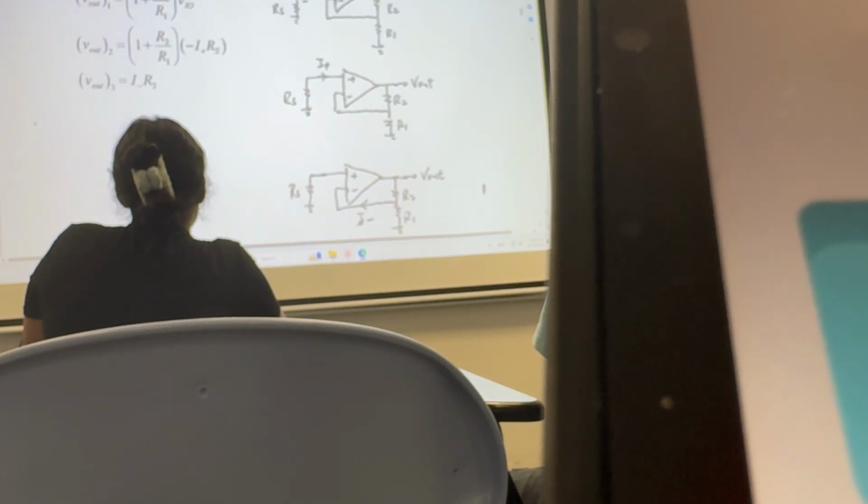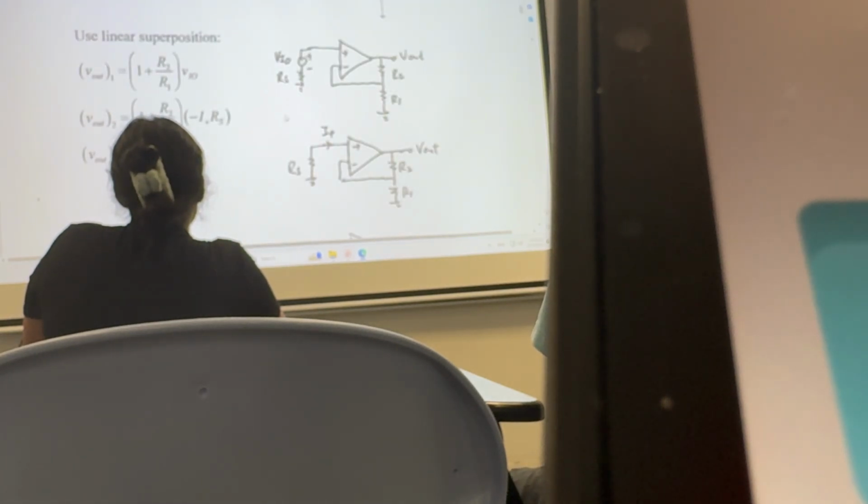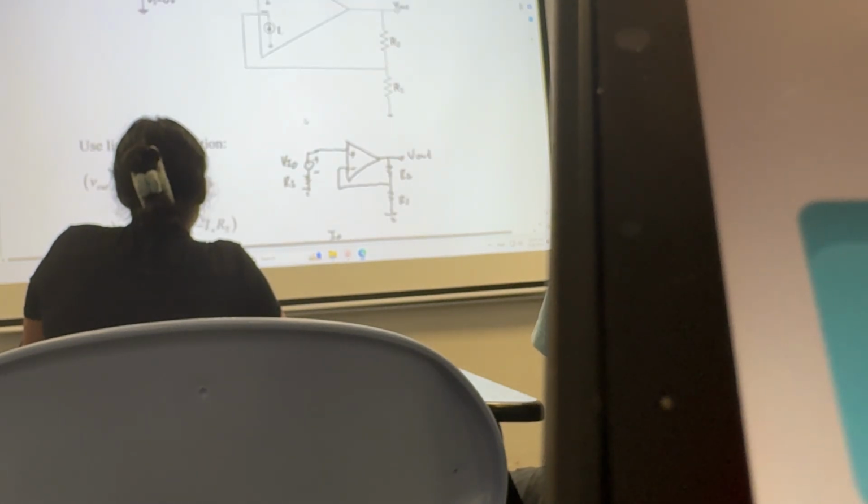After you solve it, you get 55K. So in other words, if your source resistor is 55K, you can cancel all the offset. So it's an offset cancellation, okay? Any question up to this part?